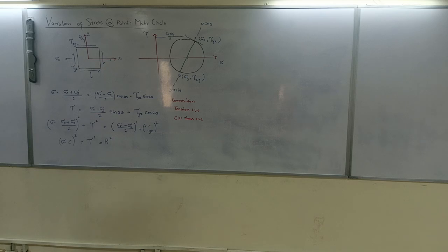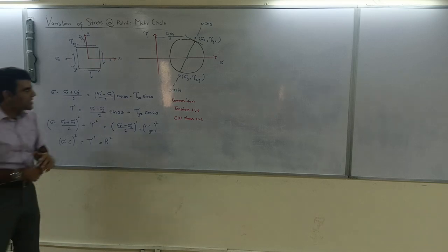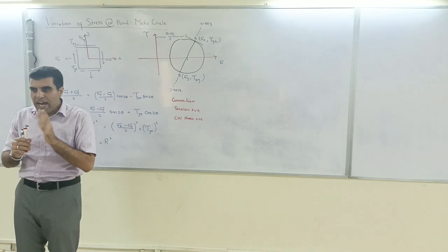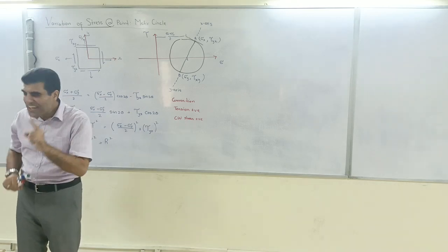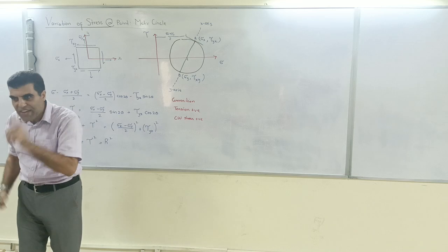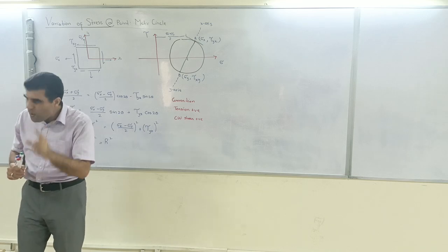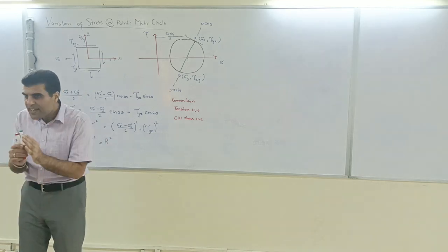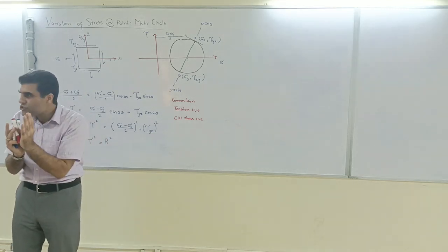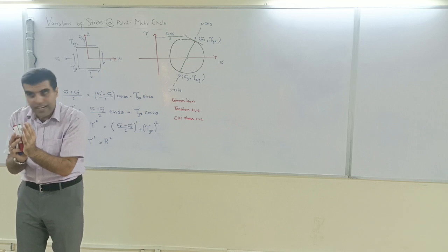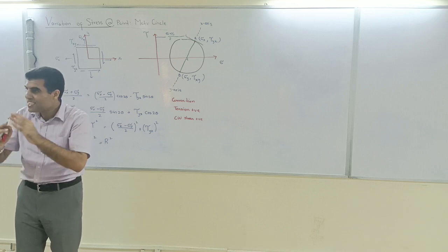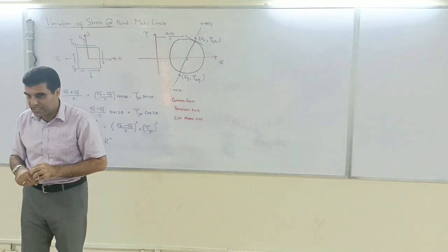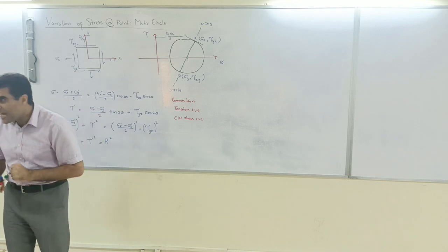There are 2 important planes which we are normally interested in. One is that plane where maximum axial stress occurs, and one is that plane where maximum shear stress occurs. Mohr circle gives you a picture that it's not possible that where your axial stress occurs, shear stress will also occur. Okay, and you can see that.